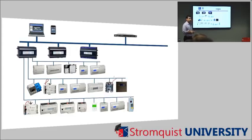Okay, so what's your solution on that one? So then we would run a LAN trunk, so we daisy chain all these LAN controllers in. Boom. We can just do one. We don't have to have multiple. We don't have to daisy chain if we don't want to, but obviously, in every case you're going to. So we have our LAN trunk and we have our BACnet trunk. We pull them into the Jace. Let's just go ahead and get ahead here for a little bit.